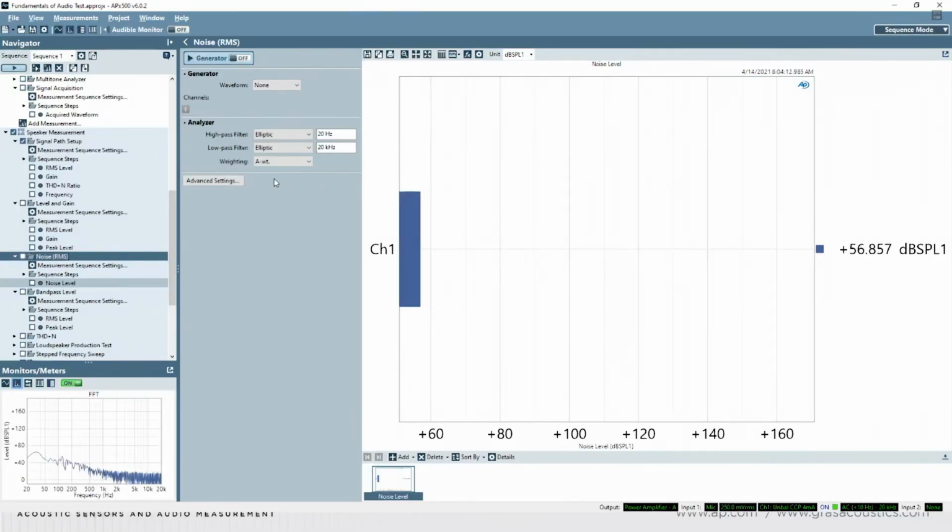However, real world audio devices have various nonlinear and time variant effects. And particularly when we talk about speakers, speakers heat up as you play a signal through them and their behavior changes. And one observation is the crest factor of a pure sine wave is so much lower than that of typical music that it will heat up a speaker much more. So there are a number of papers that have been published about the subject of measuring things like speakers with signals that more closely approximate the crest factor of music in order to see a more representational response from the device under test.